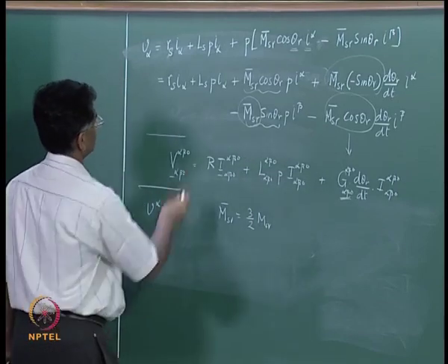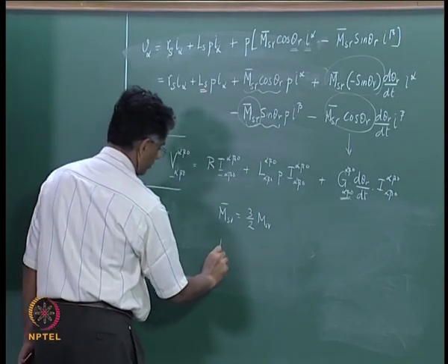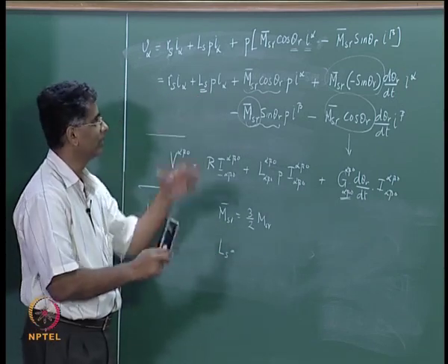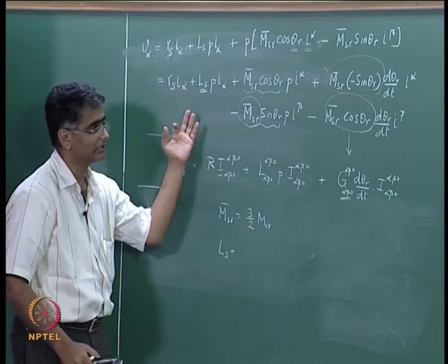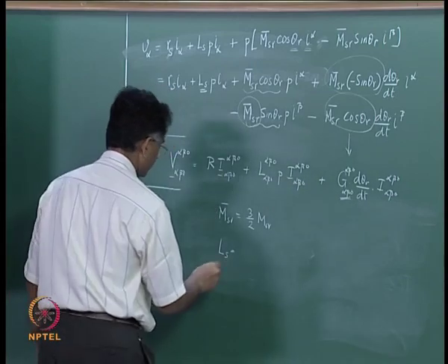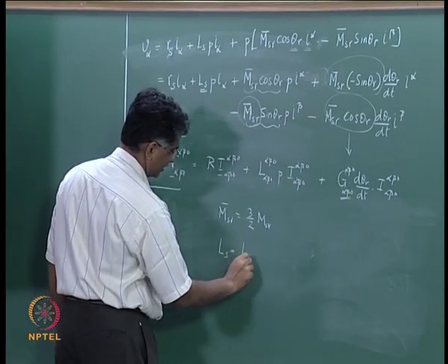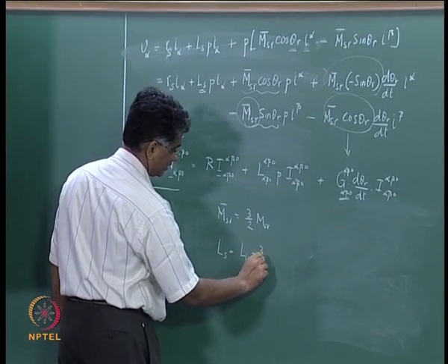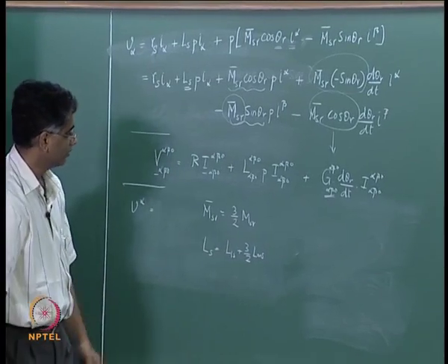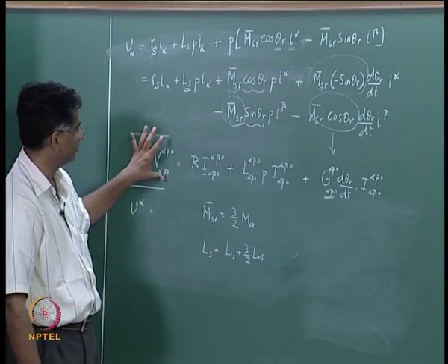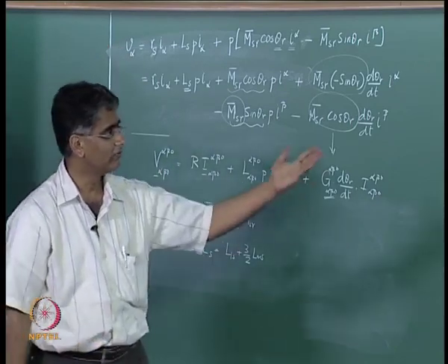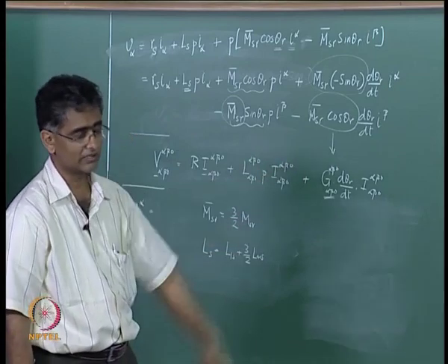Similarly, for this inductance Ls, we have written the self inductance here, which would be a leakage inductance along with the magnetizing inductance, and we found that Ls is nothing but the leakage inductance plus 3 by 2 times the magnetizing inductance. So, if we remember these things, then the expression for the 2 phase machine can be written directly by looking at the 2 phase axis.